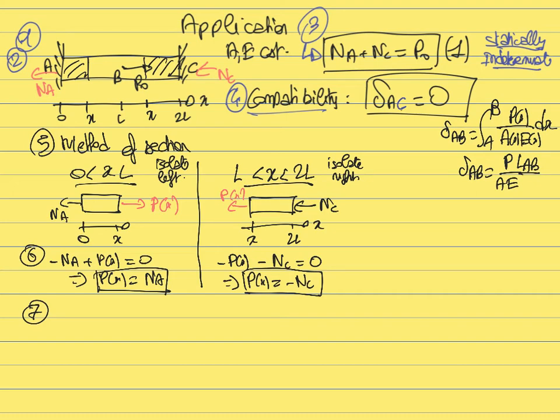However, there is one thing that we can use, which is that the load, although it depends on x, is constant between 0 and L and between L and 2L. So here we can use one property of the integral, which is that if we calculate the integral of a function between a and c, we can say that this integral is the integral of this function between a and b plus this integral between b and c. So that's the additivity of the integral. We can always separate a given integral into two integrals by integrating over different portions.